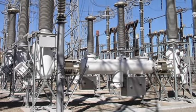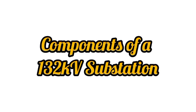Hybrid substations. Hybrid substations combine both AIS and GIS elements, offering flexibility in design and cost. This type is often used when some equipment needs to be compact, for example transformers, while others, for example circuit breakers, can be installed outdoors. Components of a 132 kV substation.